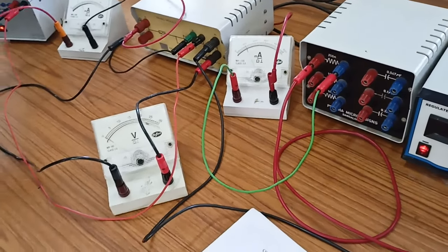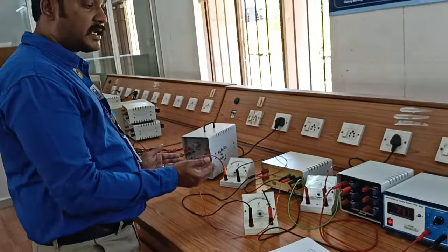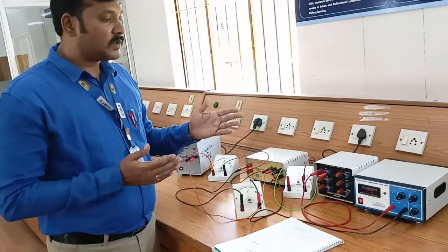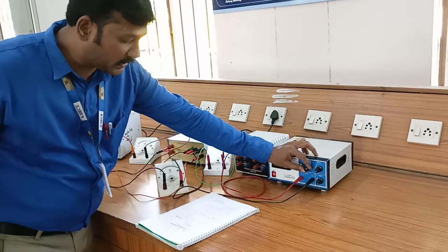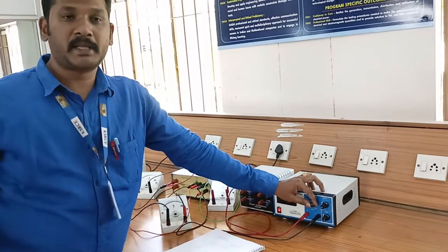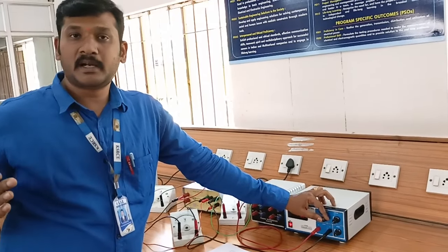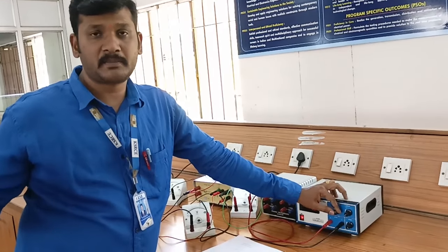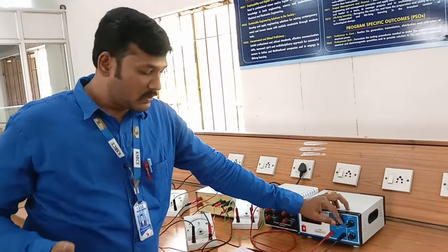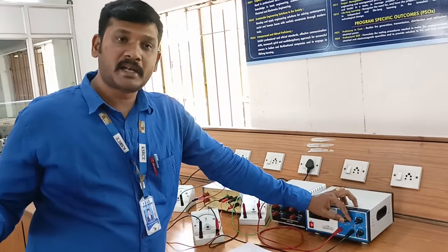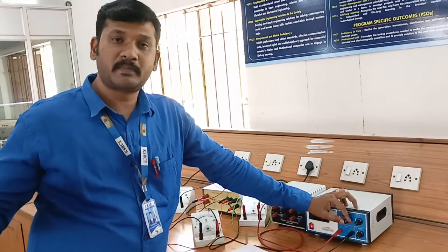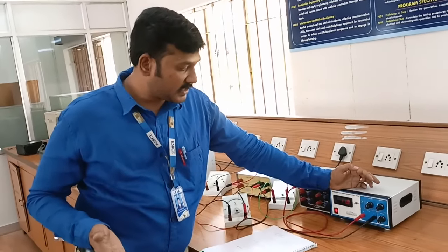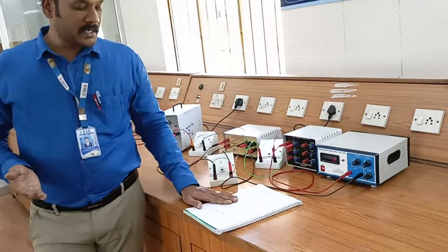Here I fixed the IG, and I am varying the voltage applied between the MT1 and MT2 terminals. First I should take the values for 4 milliampere or 3 milliampere current. After that I should set the gate current to a higher value, maybe 4 or 5. When you increase the gate current of this triac, it automatically reduces the breakdown voltage, the forward breakdown voltage or reverse breakdown voltage of the triac. Here I am going to tabulate these values.